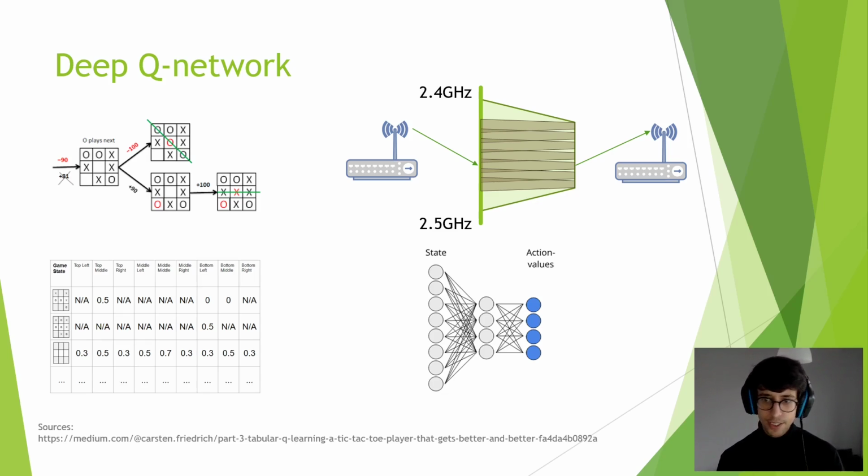Considering that at each step we can sense one of, let's say, 16 channels, and each of them can be in two states, either congested or not congested, we keep a vector of 16 previous attempts. We'll need 2 times 16 to the power of 16, which is 10 to the power of 24 possible states, which is a ton. And then for each of them, we also need a record of all possible actions. And then we need to visit each of those options enough times for the algorithm to converge.